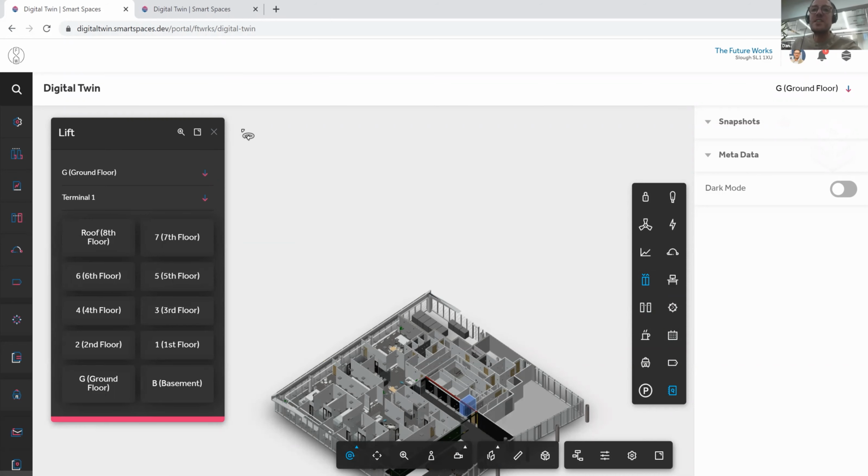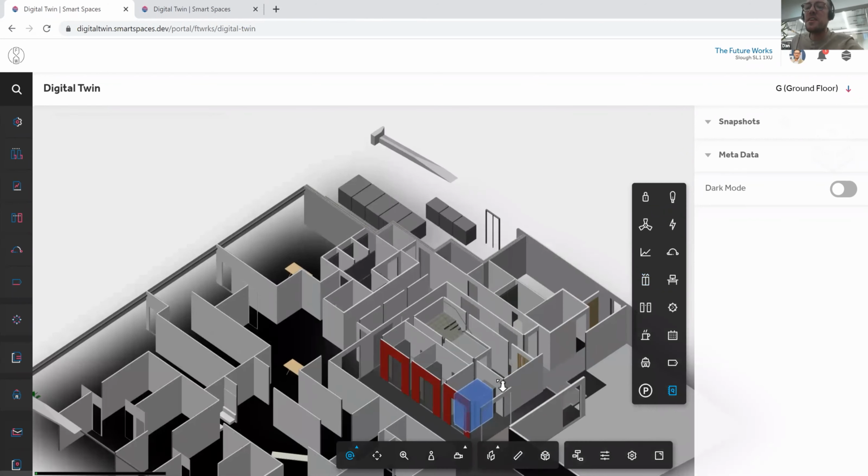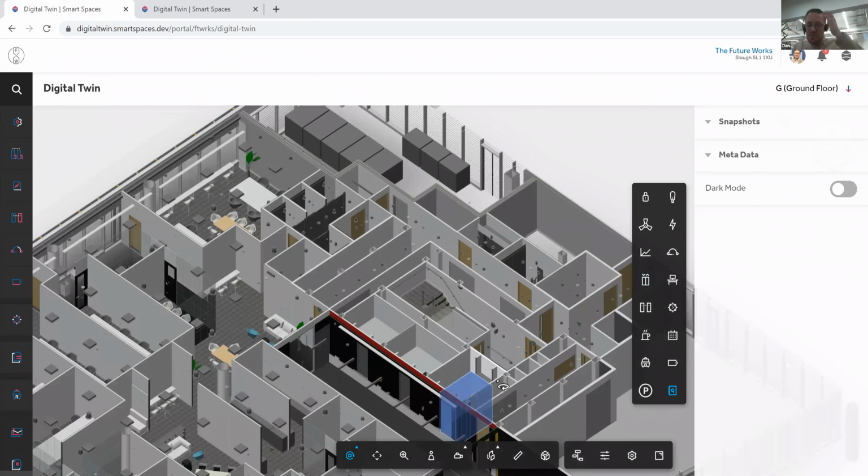We frequently find chillers on the roof of buildings. Some of the chillers never come into sequence because it's only when the building's at full load. What we can do is resequence them, so the one that has got less miles starts to get used more. And I think we will definitely move away from sort of time-based servicing to in-use, and so looking at actually how many miles or how many times that something's been used, rather than just because it's 6 months replacing filters or bearings unnecessarily. Yeah, absolutely. Much more efficient use of the assets.